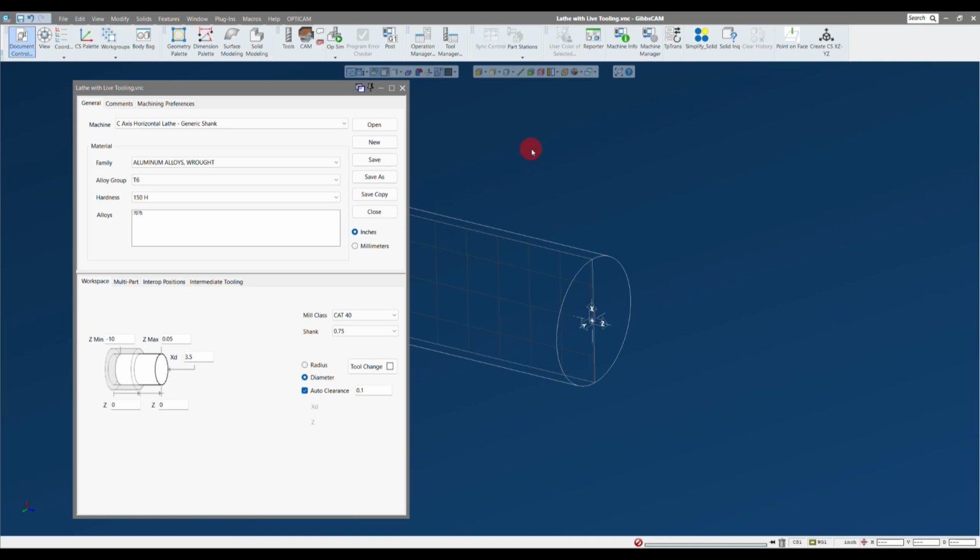It sets up the axis configuration for the machine, so the software knows that it has an x-axis, a z-axis, a y, the rotary for the c-axis. It lets the machine know the kinematics of the machine and sets that up in the background. So it's always highly recommended that you select the MDD towards the beginning of the process and not switch horses midstream. While it is possible, there's a lot of things you may need to check, and it could cause some conflicts later on down the road.